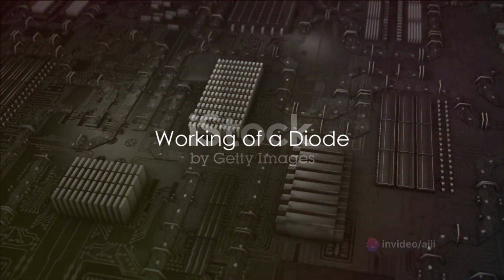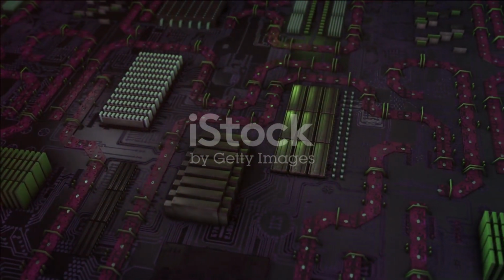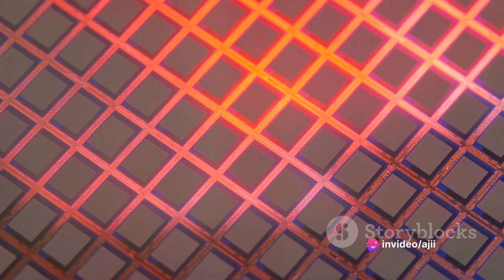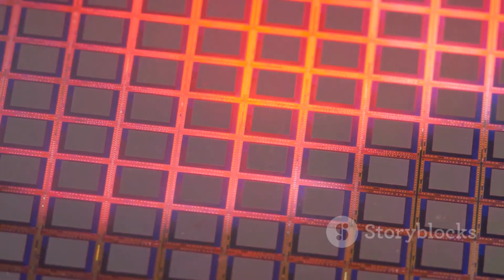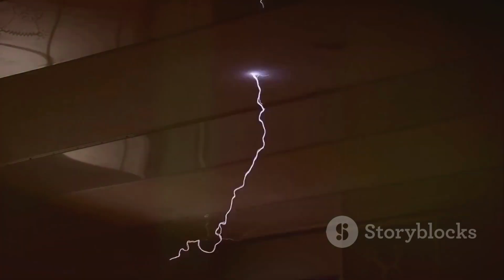Diodes work due to their unique semiconductor properties. To understand how a diode functions, we need to delve a bit into its atomic structure. Inside a diode, we find two distinct types of semiconductor material. One is N-type, which carries a negative charge, and the other is P-type, carrying a positive charge. In the N-type material, free electrons are the majority carriers, while in the P-type material there are holes, or absence of electrons, which are the majority carriers. These two materials are joined together, creating a junction in the middle.